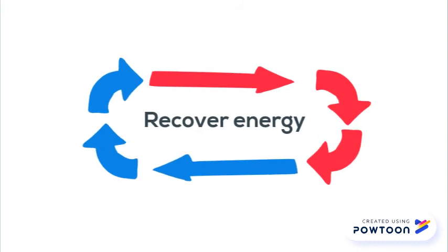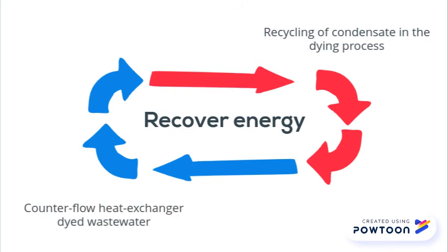In cooling processes, a lot of heat is wasted. This heat can be recycled and used to heat the water needed in the rinsing and dyeing processes. Over 60% of energy can be saved by recycling heat in this process. This can be managed by recycling of condensate in the dyeing process or a counterflow heat exchanger.